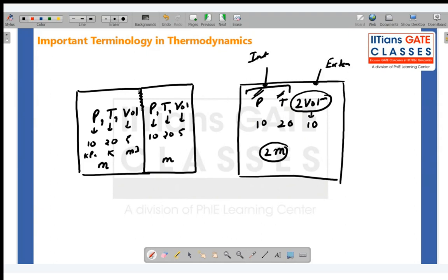Now, Bhaveshri was asking how a specific extensive property is an intensive property. It's simple. You see, H is equal to m Cp T. This depends on M. Now if I divide this by M, this is also divided by M. So what is the final expression? You will have Cp into T.